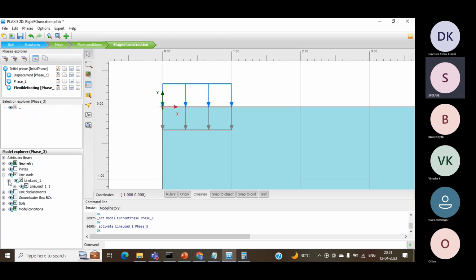And if you expand the line load here, this is in the negative direction. Now this is where I would like to apply it as minus 188. The problem is that you got it as 590 kilonewtons, but what you need to apply is the 590 kilonewtons divided by pi, which gives you what you need to apply. So 188 kilonewtons is the load that you need to apply here. Once you apply this particular load, now you try to calculate this one.